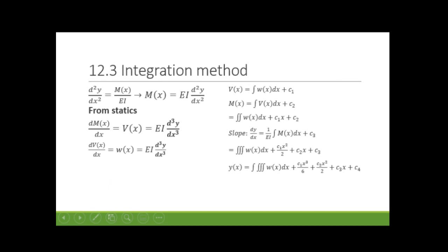So from statics, you remember dMx over dx. If we take the derivative of the moment with respect to x, we obtain the shear force Vx. So if we write this relationship into the upper function, we obtain that shear force is EI times the third order derivative of the elastic curve function.